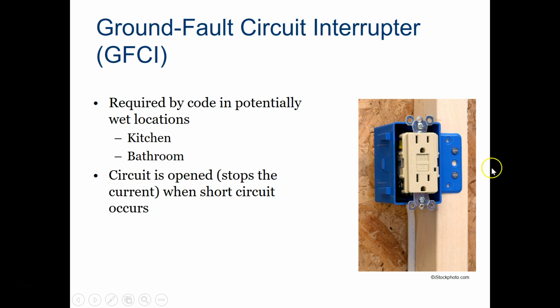And if there is a short that happens, meaning like there's a connection between the hot and the ground or the hot and the neutral, that it's pulling too much power, it will trip this little built-in circuit breaker right in the outlet before it even goes the whole way back to the main circuit breaker, which is only looking for overloading the circuit. So even if it wasn't pulling more than it needed to, but if it sees that drop of voltage across those two, then it will trip that little circuit breaker and potentially save your life so that you're not going to electrocute yourself.